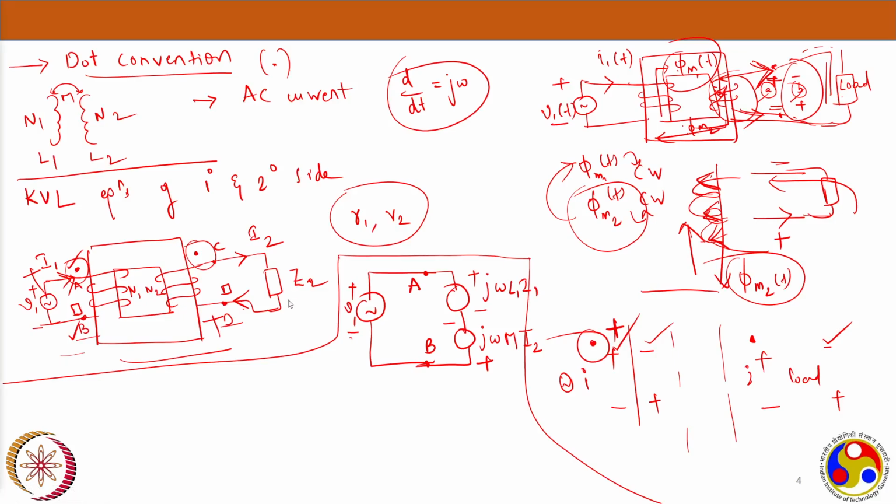Now, similarly, this is the primary side equivalent circuit, right? Yes, sir. Can we say it another way? Because in C, the current is leaving the dot, so the mutual voltage, because of this change in the current, on the primary side will enter the dot. If you are trying to backtrack it, I mean, if the current is leaving from the C, the cause due to that is entering at the dot. So yeah, that's also okay.